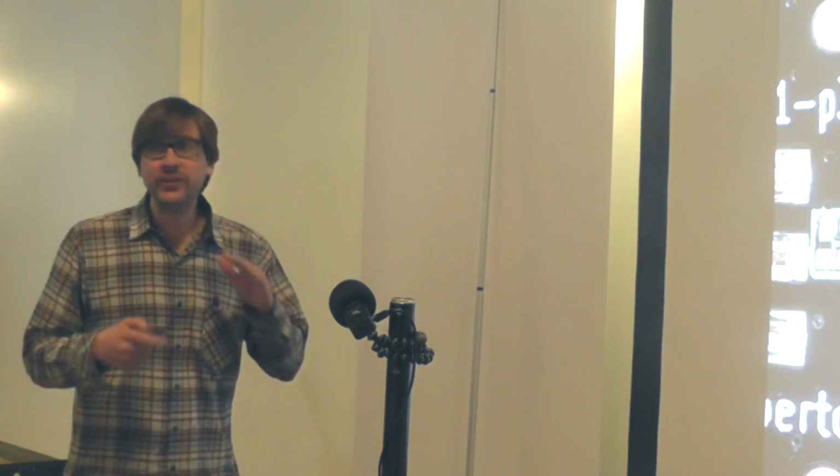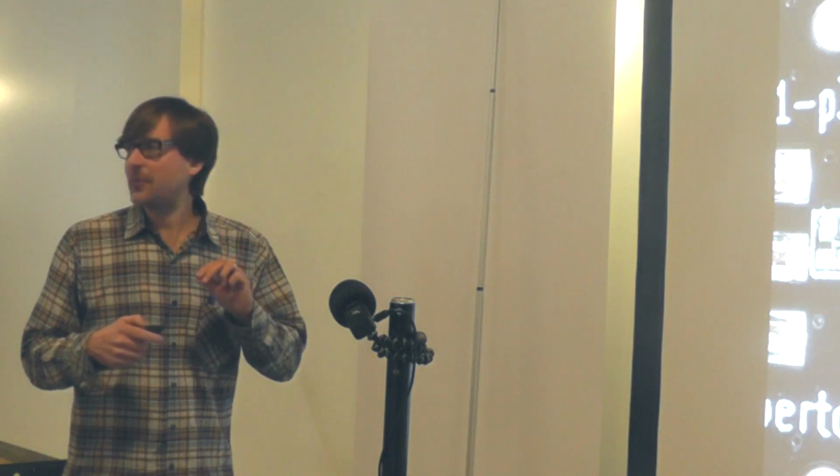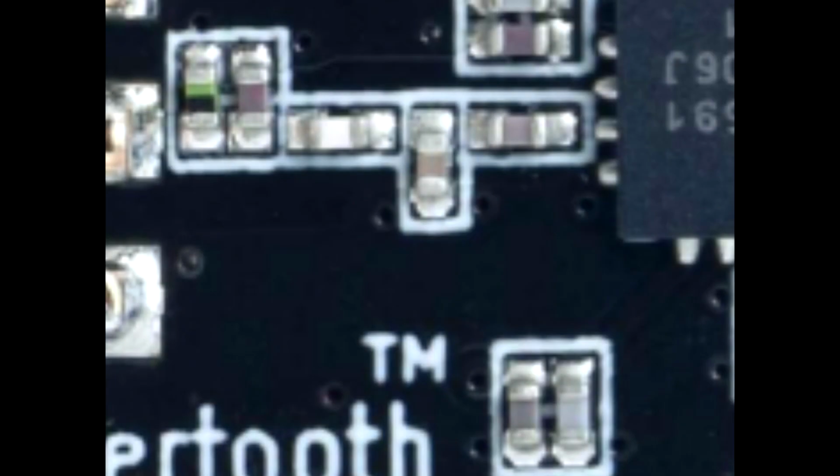Now, it is important that it be copied very precisely. For example, there are these components down here, these passives, that have a particular transmission line length and width, because the transmission line characteristics matter. And so the manufacturer actually specified the PCB stack up and exactly how far this transmission line should be and so forth. So I copied it very deliberately, exactly like the manufacturer said, and it worked great.